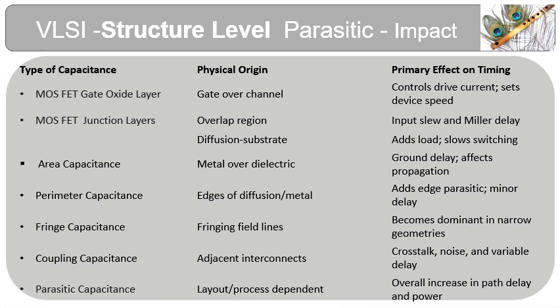Every functional element in VLSI, whether a MOSFET, interconnect, or contact, is made of real physical materials that possess finite resistivity and dielectric properties. These materials do not behave ideally; instead, they introduce parasitic resistance, capacitance and inductance as an inherent part of their structure. Electric and magnetic fields do not stop sharply at geometric boundaries but extend into nearby regions, giving rise to fringe and coupling effects.